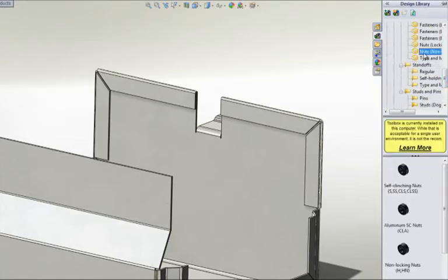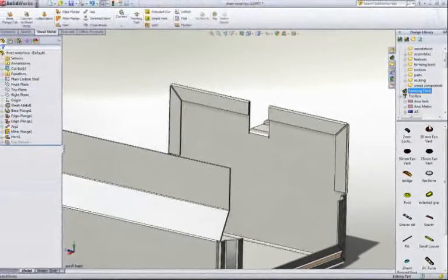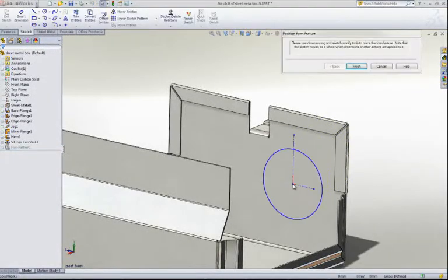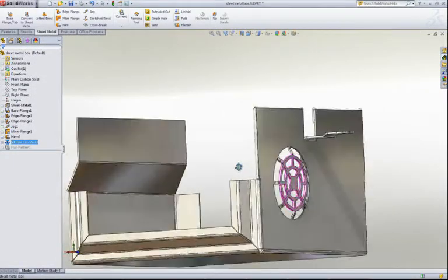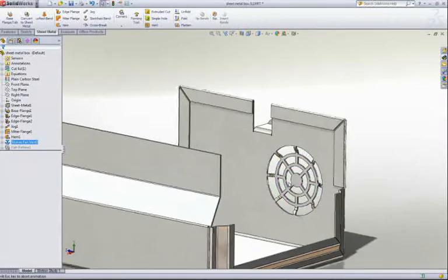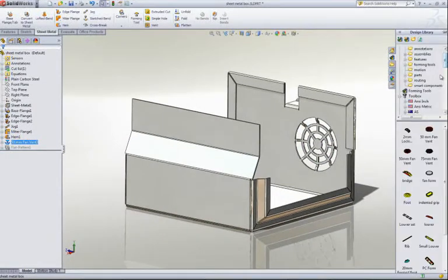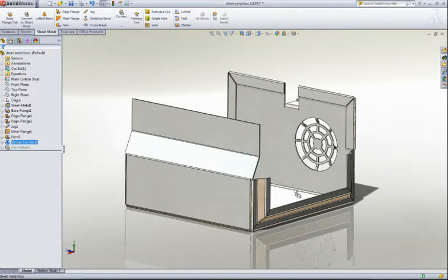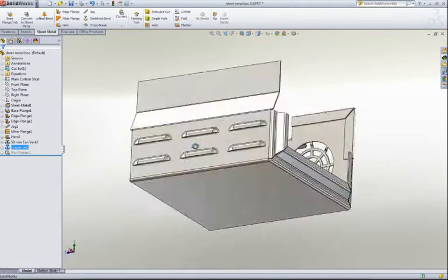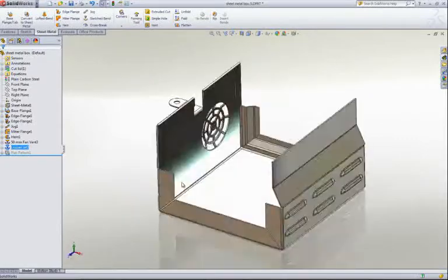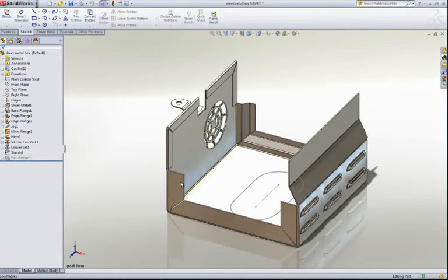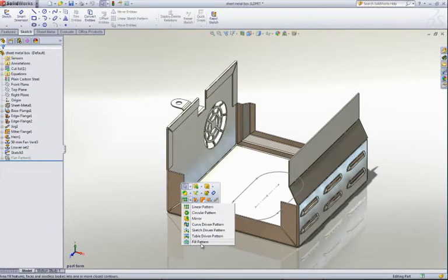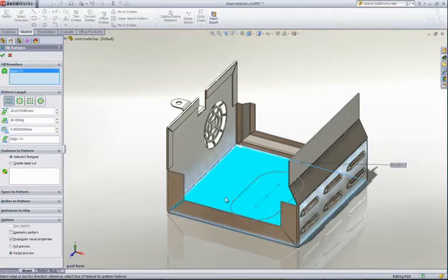ribs. The library also contains many common sheet metal fasteners like PEM nuts, standoffs, and studs. Custom libraries can be created to match your in-house tooling and are applied to the part with a simple drag and drop. As we add this louver set, it's easy to see and toggle which side of the tool is struck. Material is deformed and lanced as defined by our standard form tool. Simple. Ventilation holes are common in sheet metal enclosures, so it must be easy to add perforations to your parts.